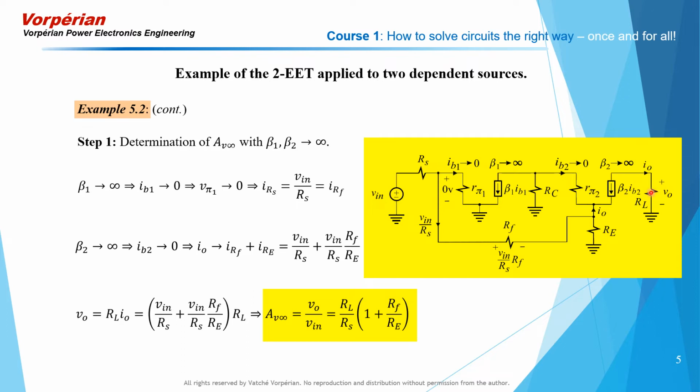You're doing so by virtue of the fact that in general the emitter current is very close to the collector current, or the output current as it is. You're sampling it and you're feeding it back and subtracting it from the input current, and you're making that error vanish to zero, so that this current here will be entirely dictated by the feedback network and the input voltage, having nothing to do with the amplifier itself. That was the whole idea of coming up with this circuit.